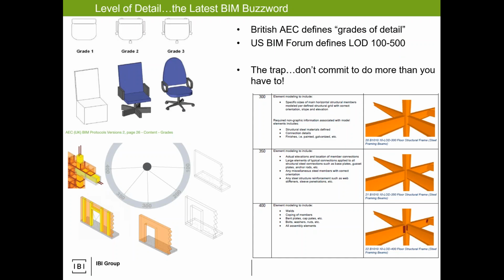Level of detail, level of development, is a term that comes up quite often. Have you guys heard of LOD 300 or anything like that? Yeah. So for me, to rationalize it, LOD 100 is your schematic, 200 is more like 60%, and 300 is the relative comfort level for us designers.